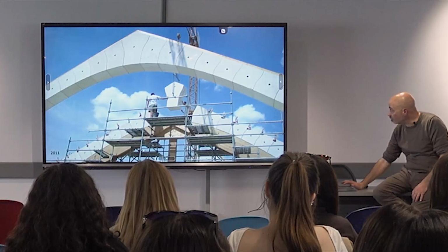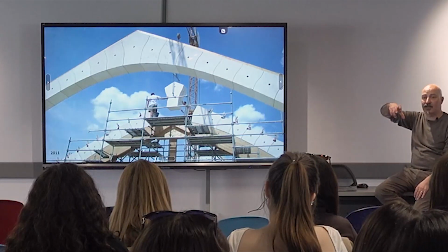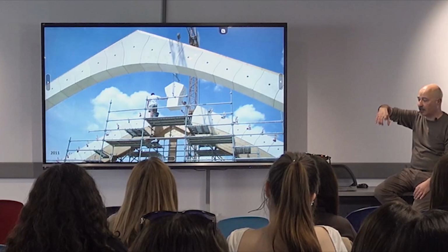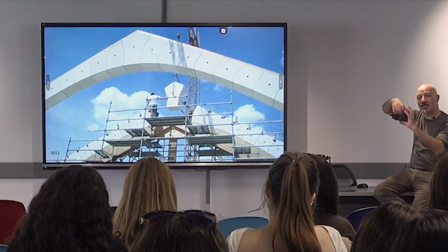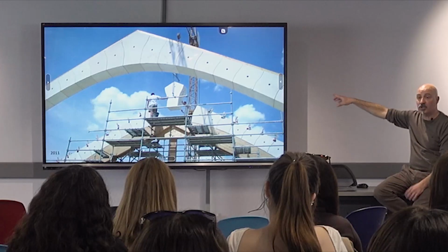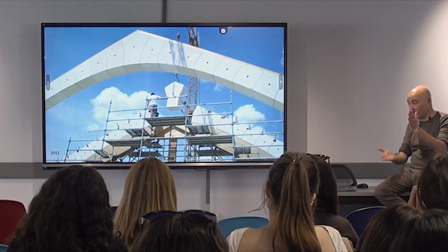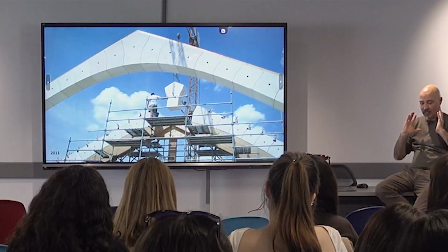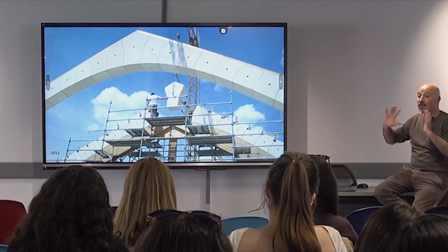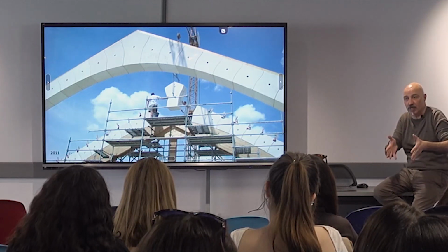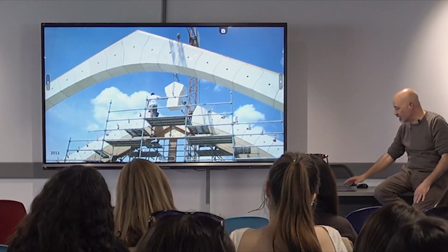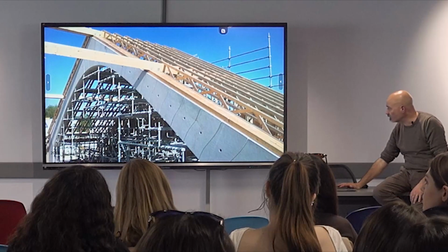So here you can see some pictures of the realization. The holes are at the barycentric part of the volume, the centroid of the volume. So thanks to this configuration, we can easily move the blocks, also huge blocks. And the junctions are not flat, but linear. And thanks to this shape, it's very easy to assemble them in the right position, only thanks to the gravity of the stone. So no kind of energy is needed to realize the building, to realize the arch.